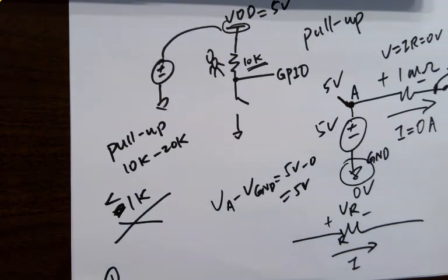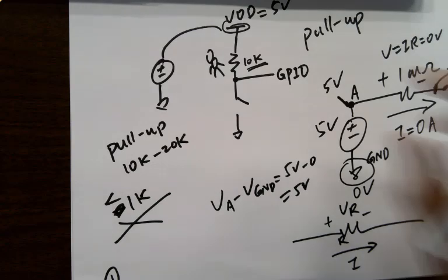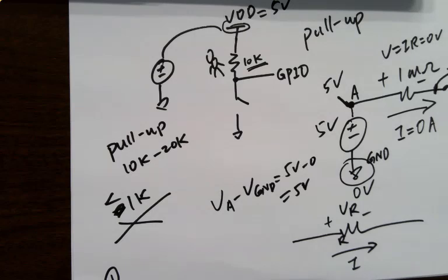It's just being used as a pull-up. It's not a functional component, or it is, but it's not that functional for the circuits, right? It's just pulling up. So 10K, 11K, 12K, 15K, 20K, all of them work. In different situations, you have to choose different resistance.